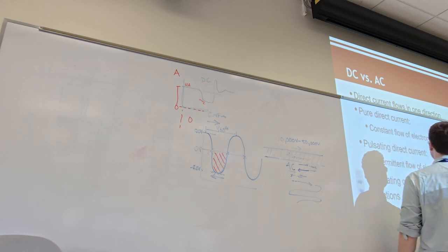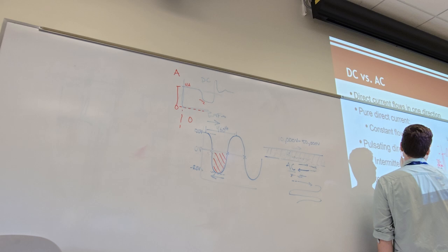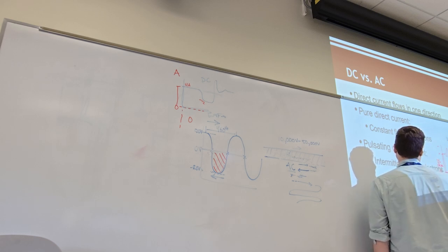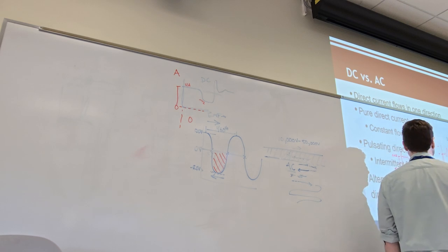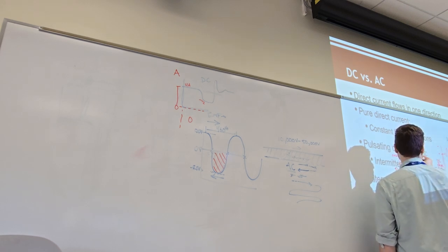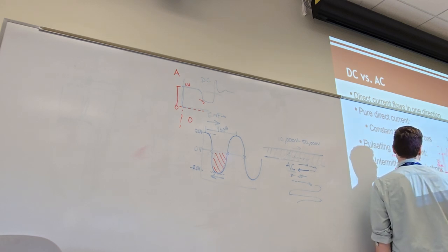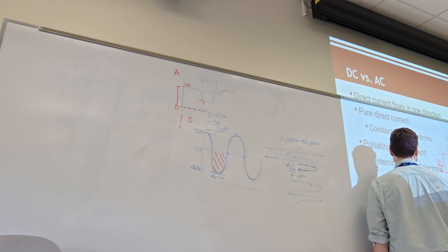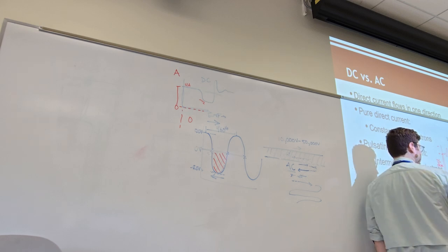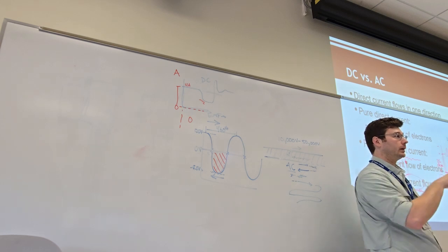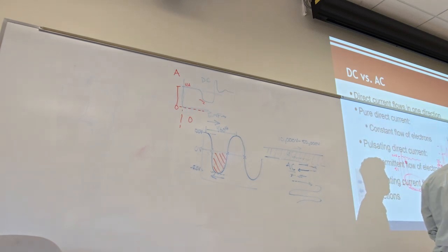If your dynamic signal is really low, you just have a little bit of change, but it's riding on top of this gigantic 5-volt signal, and your little signal is just 0.1 volts different, it's going to be really hard to measure, because when you try to zoom in with an oscilloscope, it's going to want to focus in on this region. But if you do the AC coupling, it will shift it down, and your signal will be really easy to read. It'll just be on the center line of your oscilloscope in AC coupled mode.